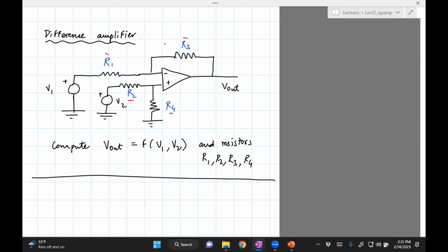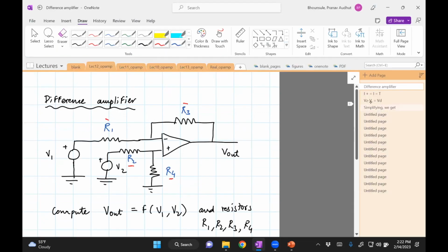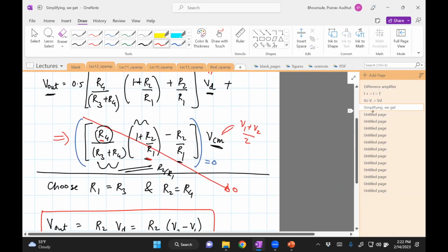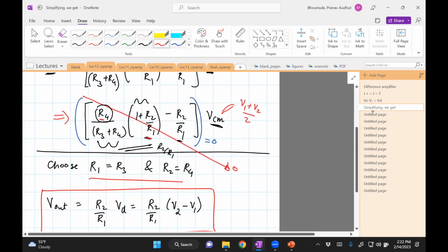Now, there's something about resistors, which is that resistors actually have a variability in them, right? So you'll have the silver or the gold band. So you cannot be assured that the resistances would be whatever it says based on the first 3 bands. The other issue is that as resistors get heated, the resistance will change with time. And if that happens, then effectively this term in the bracket will not go to 0 because the resistors are not perfectly matched.